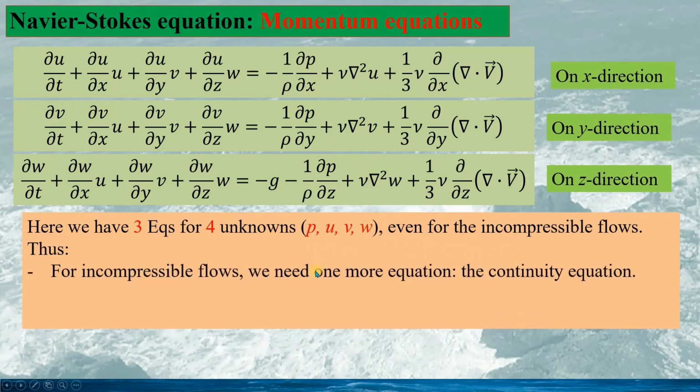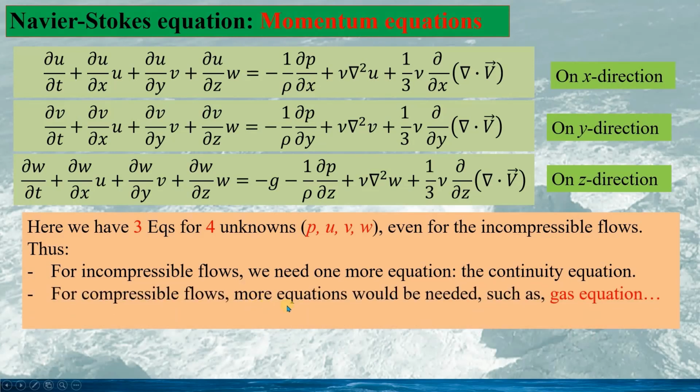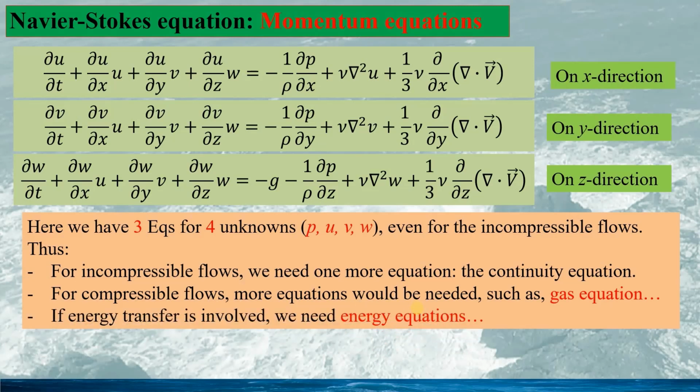Thus, for incompressible flows, for a complete fluid dynamics, we need one more equation, and the equation would be the continuity equation. For compressible flows, more equations would be needed, such as the gas equation for the compressible air. And if energy transfer is involved in the fluid dynamics, we need energy equations.